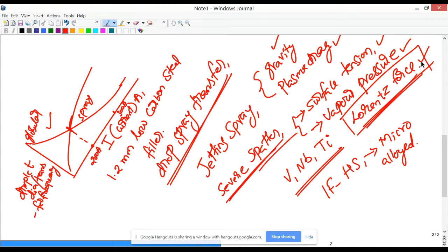In assignment 1, question 10, when non-transformed austenite transforms to lower bainite, we can expect cementite precipitation, and also intra-lath precipitation of cementite in between the ferrite laths. Okay, good.